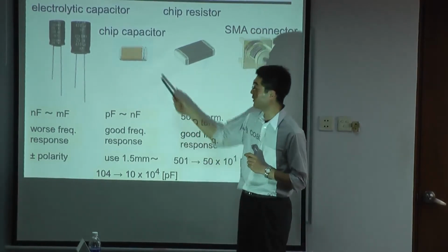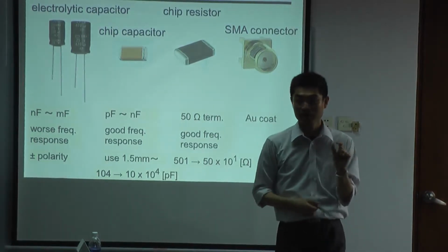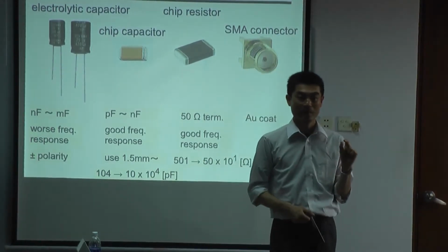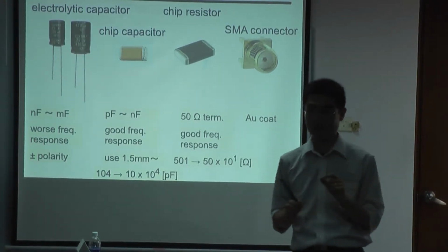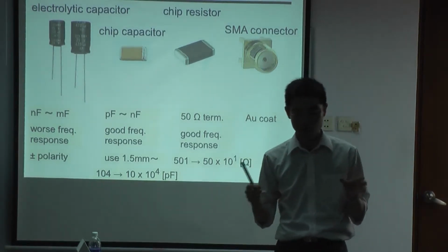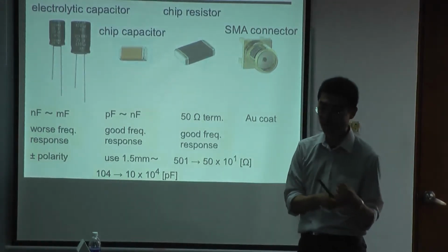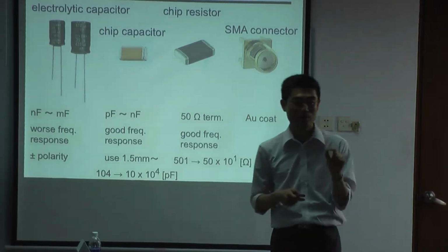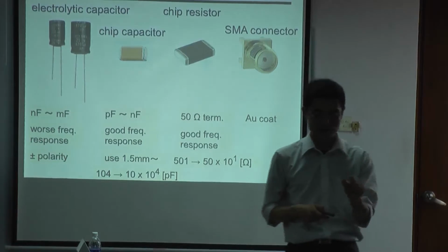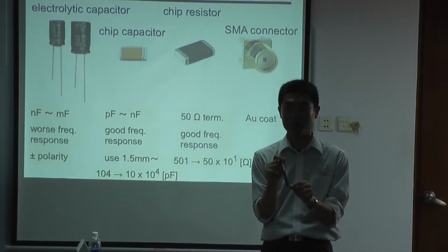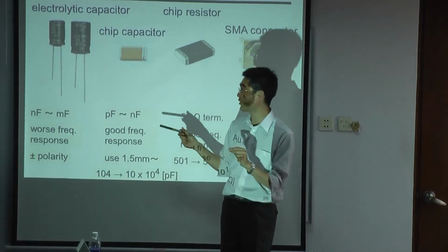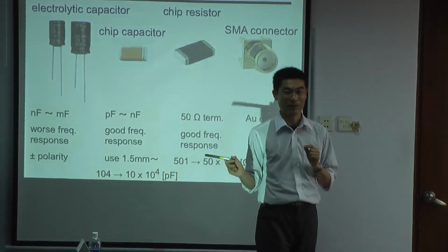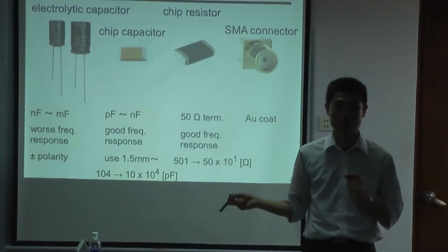And this is a chip capacitor and its size. We have many sizes, such as 1 millimeter, 0.9, and 0.5 millimeters. For recent cellular phones, we want to make the PCB board smaller. But when you assemble this capacitor by yourself, the smaller capacitor is very difficult to handle. We use tweezers to handle it, and solder and heat to attach it to the board. So I recommend you use a relatively larger one, larger than 1.5 millimeters. I often use 1.5 millimeter chip capacitors.